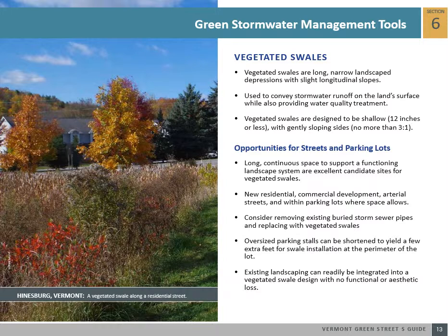Swales are excellent choices for new residential and commercial development and can be retrofitted along arterial streets and within parking lots where space allows. Parking lots and certain streets that have long, continuous space to support a functioning landscape system are excellent candidate sites for vegetated swales.